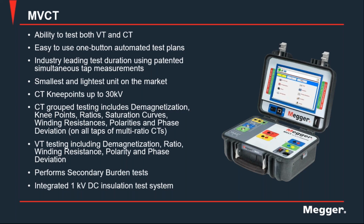Or you can use an alternate method to saturate. Instead of applying AC voltage, you apply AC current and measure the saturation through that system. We have presentations that talk about that method. So it's a lighter instrument because now you don't have a transformer that goes up to 2 kilovolts.